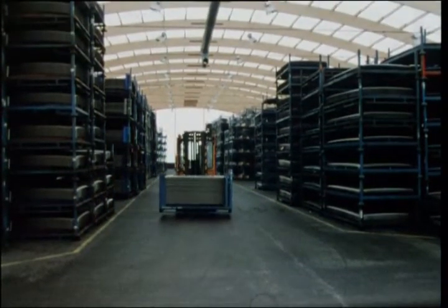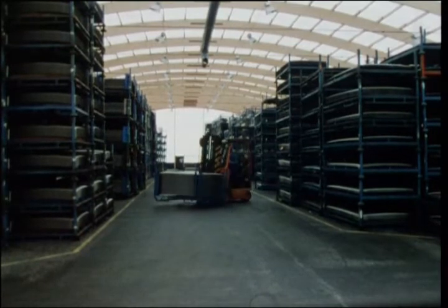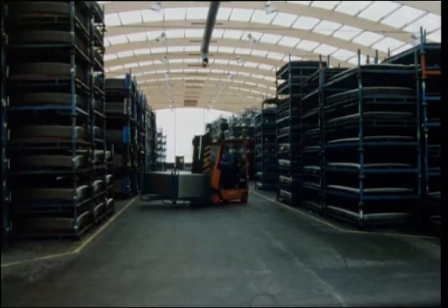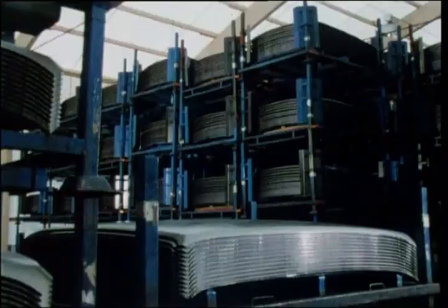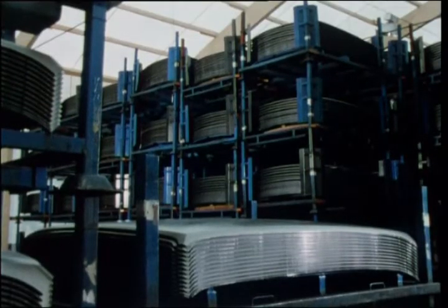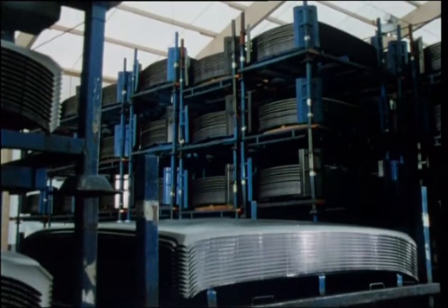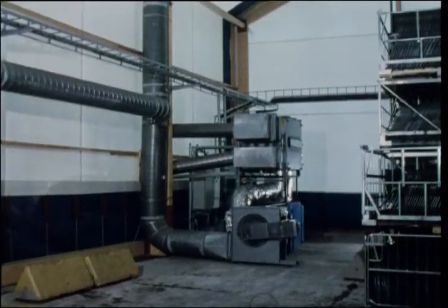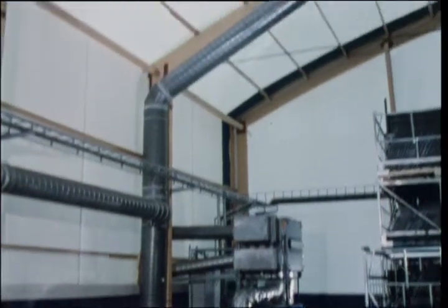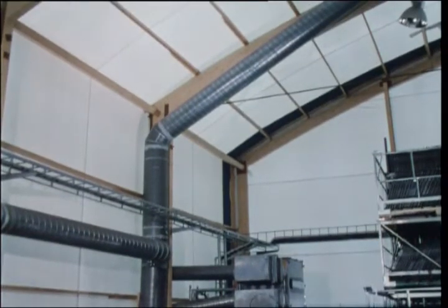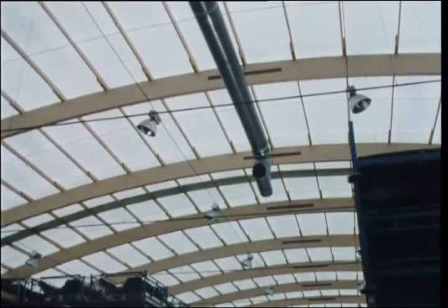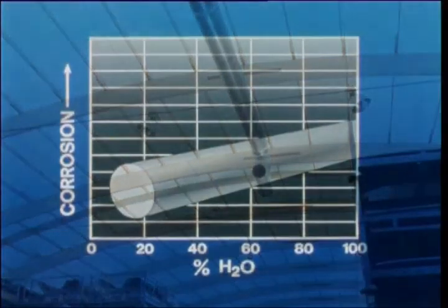Now, where steel is exposed to the atmosphere and oxygen obviously cannot be removed, rusting can be prevented by reducing the humidity and preventing the formation of liquid water. This is achieved by circulating the air through a dehumidifier, and a positive air pressure is maintained in the room. Because it is not necessary to remove all the moisture from the air, corrosion can be controlled economically.